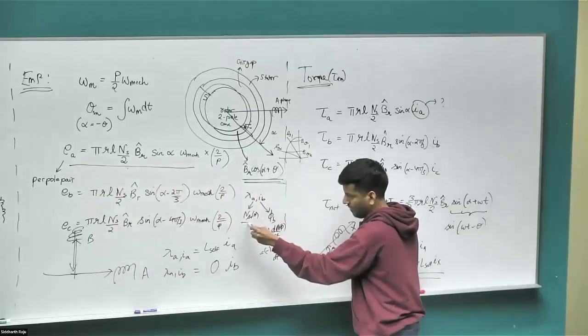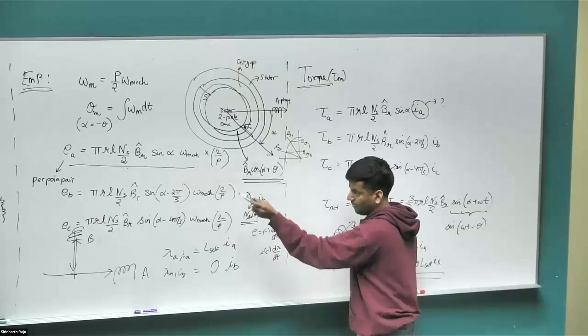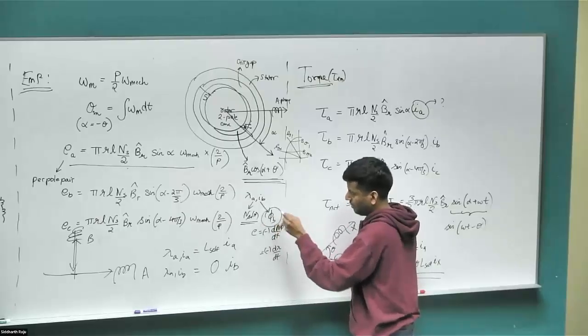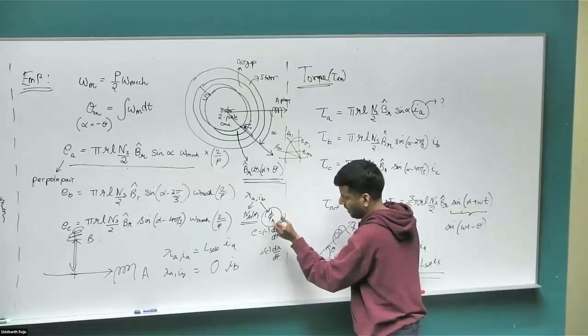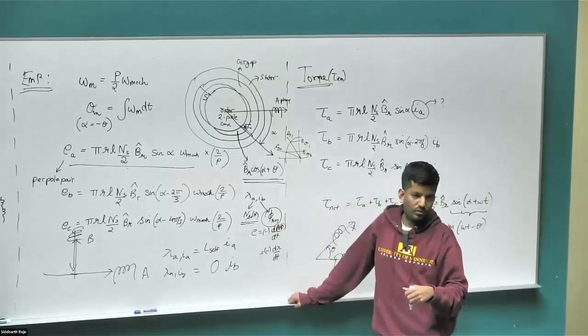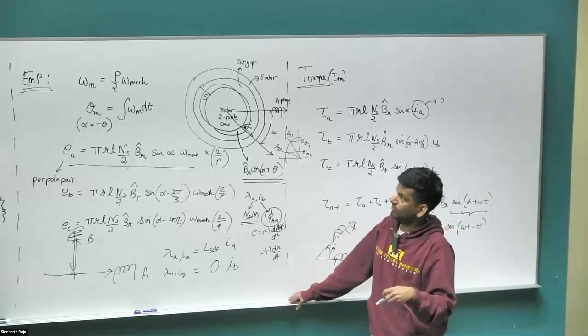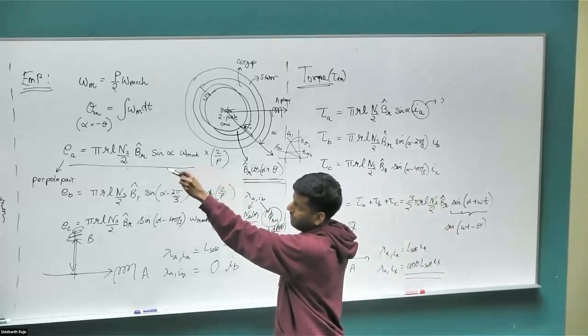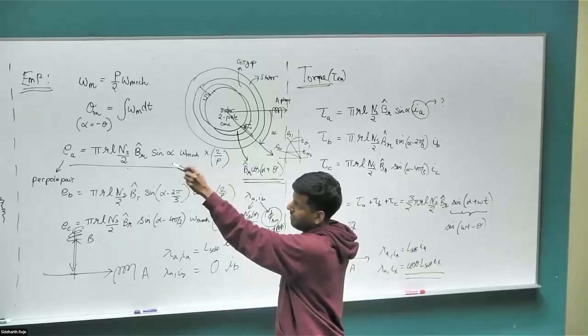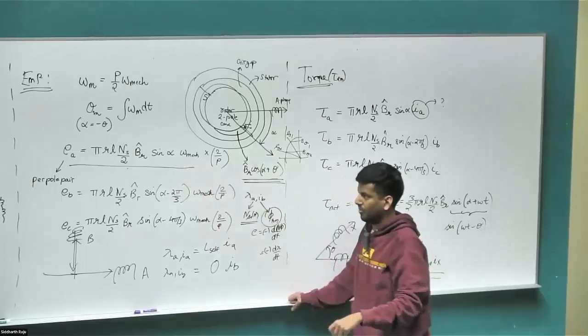We go back to the same expression. This term remains the same from the flux linkage derivation for the inductance. This phi B would now be replaced instead by phi of the rotor magnet. That's all the difference is. The phi B came from that term right there, BA of theta instead of BB of theta, which would have been mu naught times PA divided by LG times I times cos of theta minus 2 pi by 3.